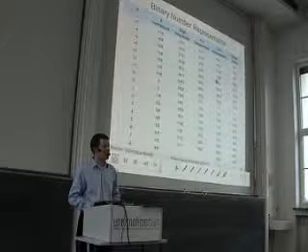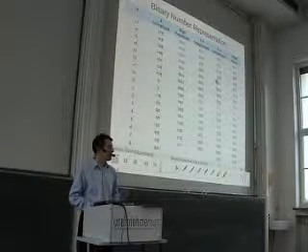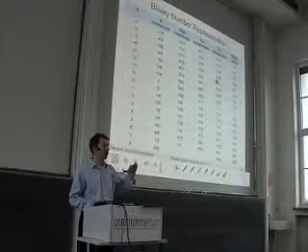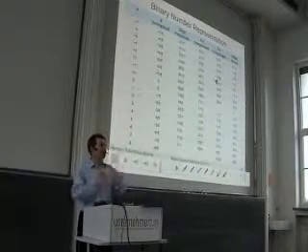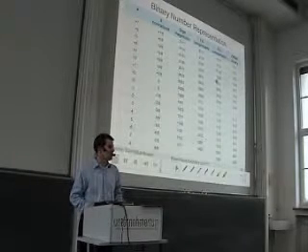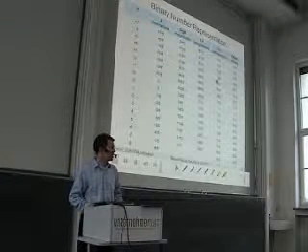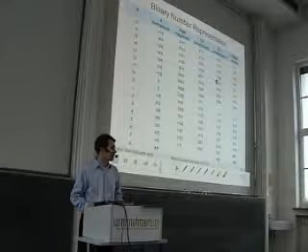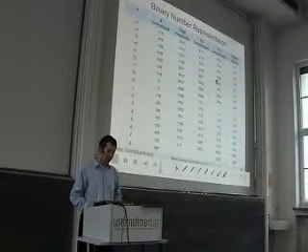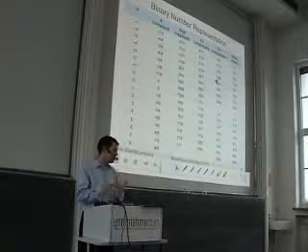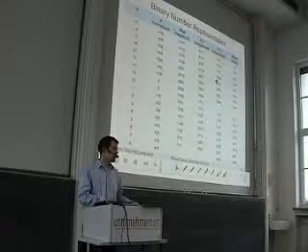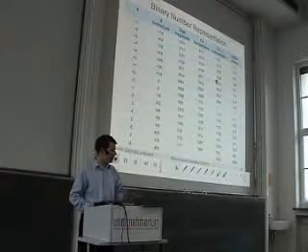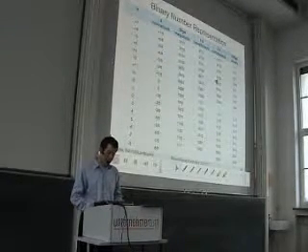This occurs, for instance, if we have a conversion where we first determine the sign, say, okay, is the voltage positive or negative, and then we work only on the absolute value of the voltage. Then naturally we end up with a sign magnitude coding. And if we want to go from the output of such an ADC, for instance, into a processor, we first have to convert this from sign magnitude to 2's complement.